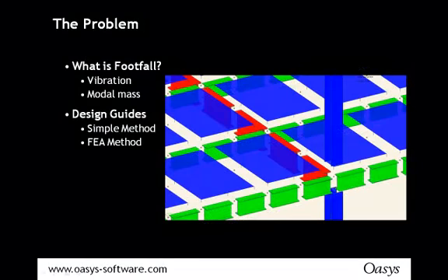And the way you model a floor, well, this is a GSA screenshot. This is a composite floor where we have the beams offset down, the slabs offset up, and because these are working together, this will automatically induce composite action in the structure for a composite floor. If it's non-composite, then that will be inappropriate.